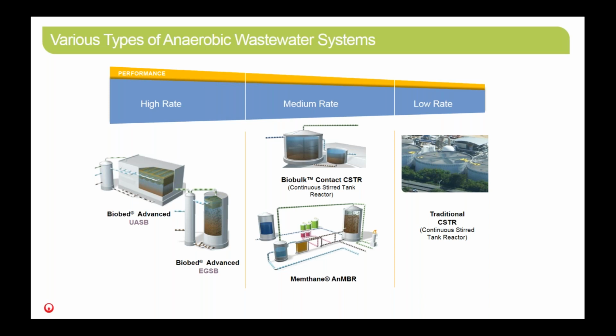So really, we typically classify our systems into three: high rate, medium rate, or low rate. That's about the loading rates that you can put into them, and then the influent decides which one of those technologies is the most applicable.